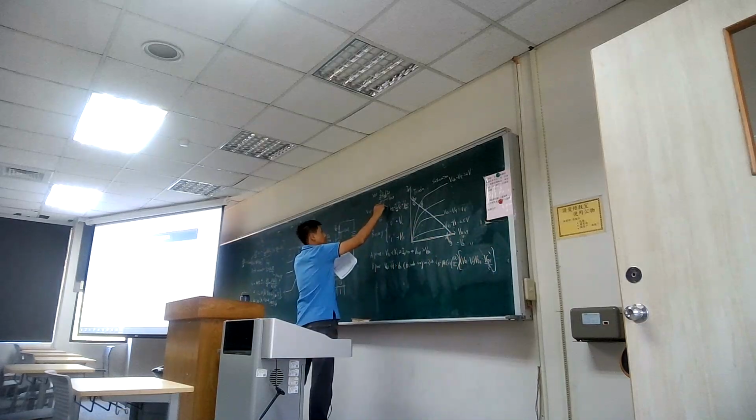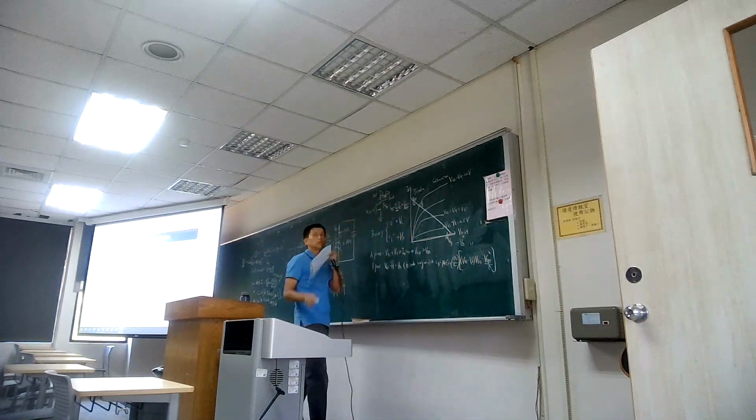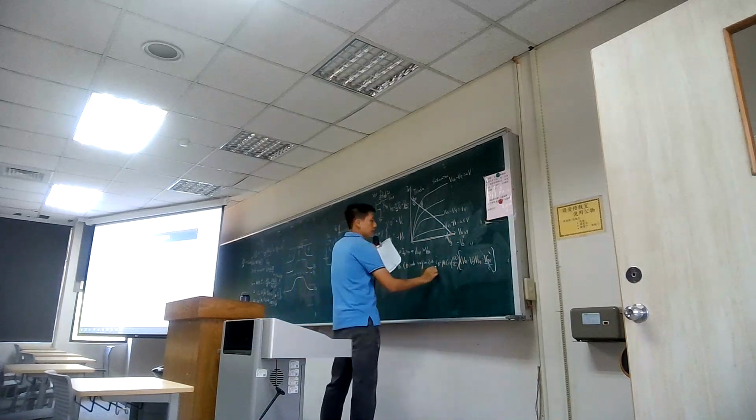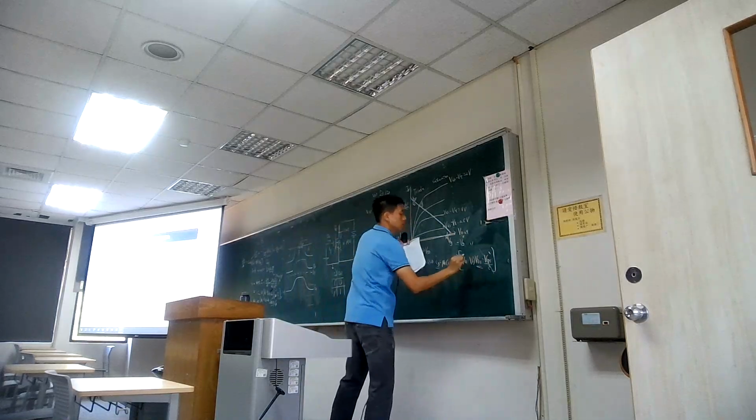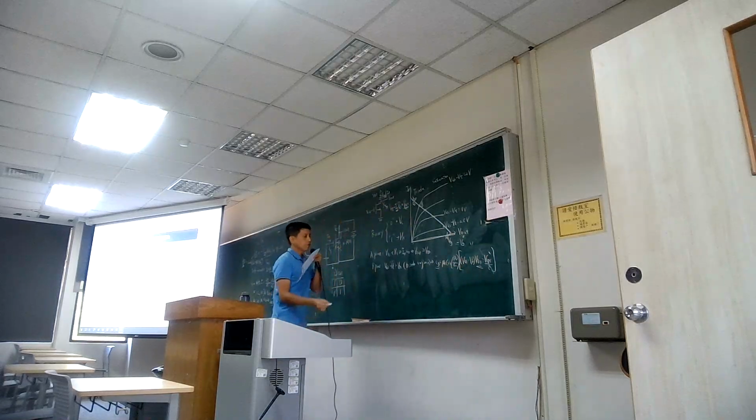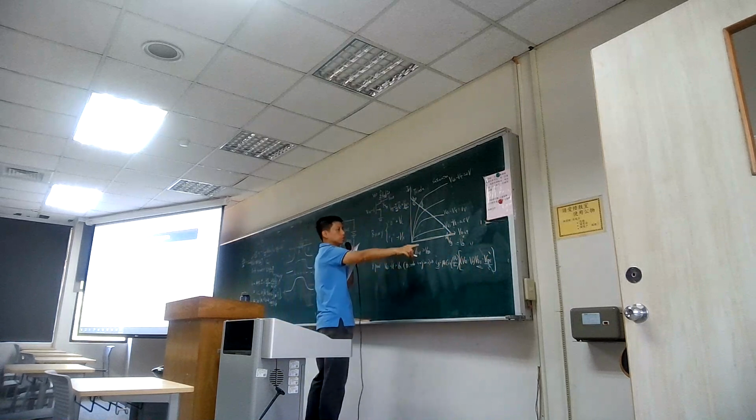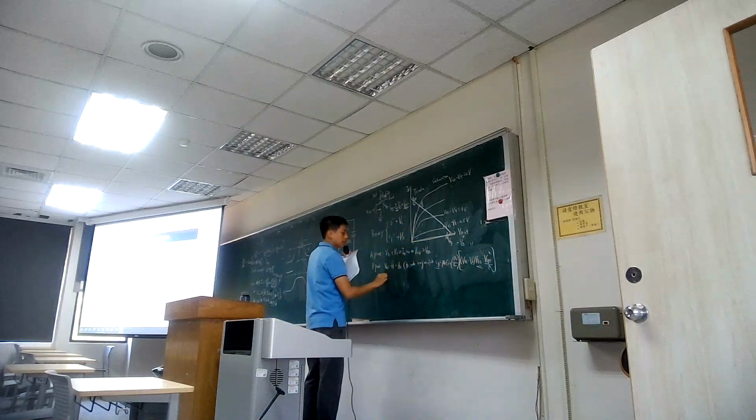And what we get here is that, okay, I want to calculate the corresponding RDS. So you can think of it just like a resistance in parallel. But why can we calculate that? Because we get ID and the VDS, the V out. Okay, so if you assume VDS is really small compared with VGS minus VT, you can simplify this equation as the linear model within this region.